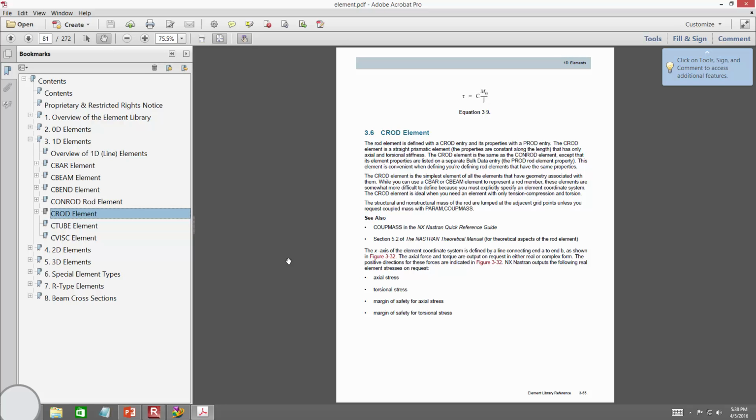The purpose is to use the right analysis tool for the right job. You see what I mean? We don't need to do a nonlinear time history analysis with geometric and material imperfections and all that if all we're trying to do is a plain truss analysis. Use the right tool for the right job.